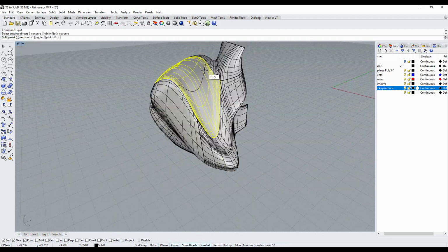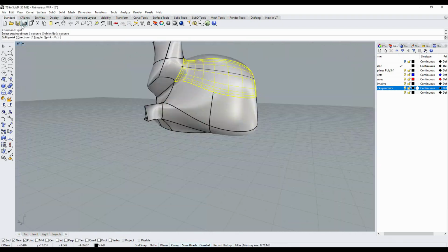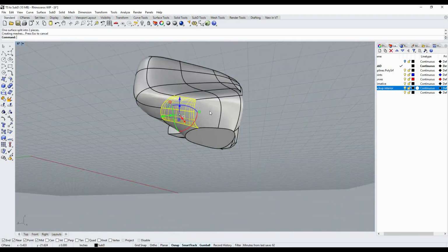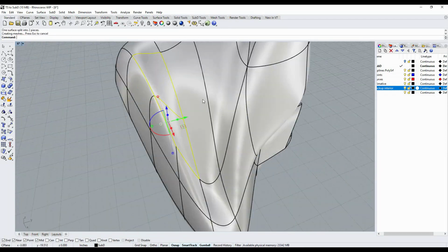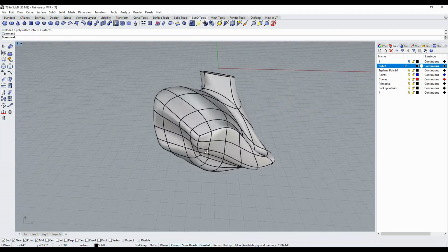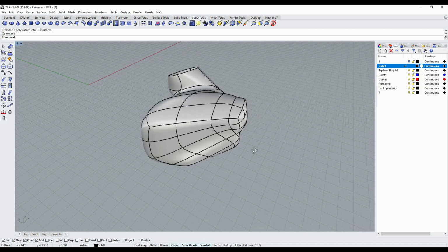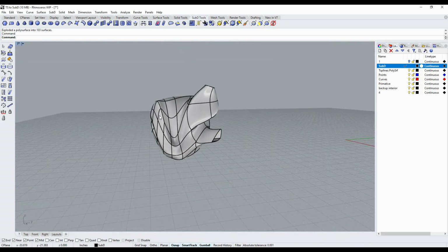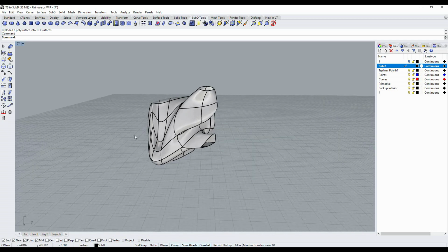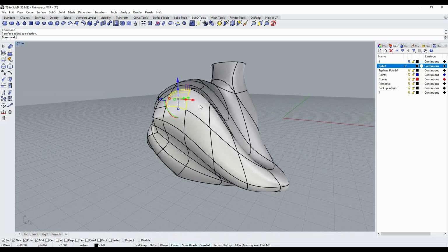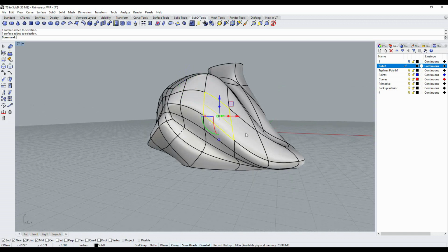Now, I'm going to go ahead and finish cutting this model into pieces that represent the original T-spline model faces. Alright, each of our surfaces has been cut into pieces that represent our original T-spline faces. Now we can go ahead and apply our methodology of drawing a SubD face for each surface.